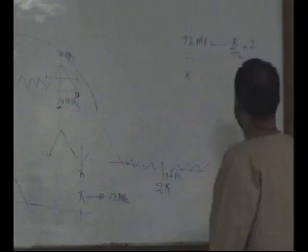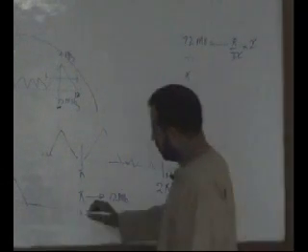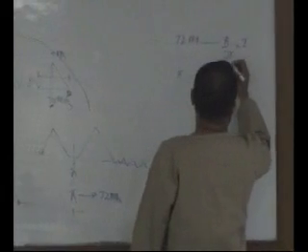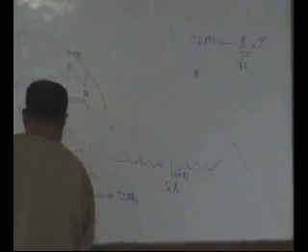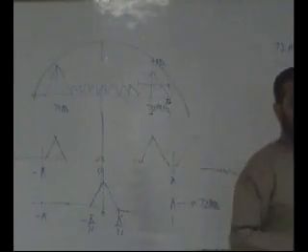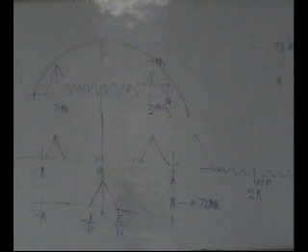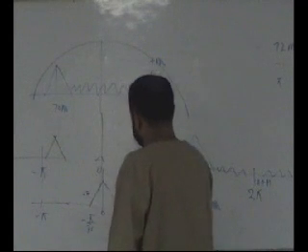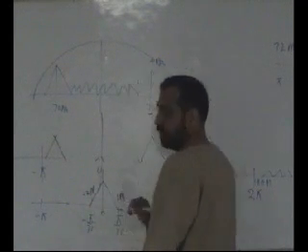So you can exactly figure out what corresponds to this frequency digitally. So this is pi over 36 to minus pi over 36. This is your spectrum, which corresponds to 2 megahertz and minus 2 megahertz.